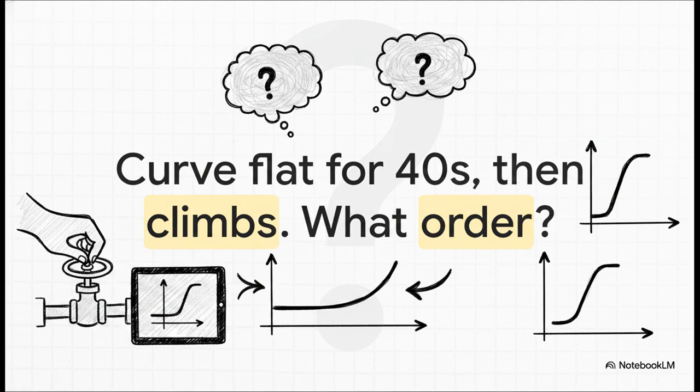All right, let's do a quick test of your new visual decoding skills. Imagine you're out in the field running a step test. You bump the valve, you stare at your screen, and the measurement curve sits completely flat for 40 seconds, just doing absolutely nothing. And then finally, it starts to climb in a slow S shape. Take a second. Are you looking at a first-order or a high-order process?